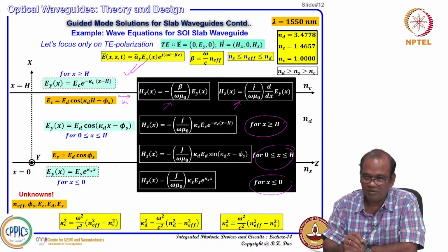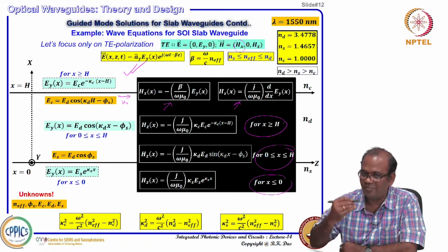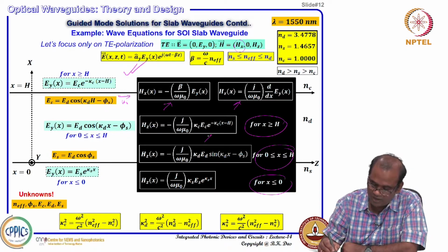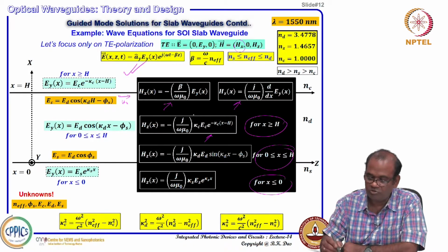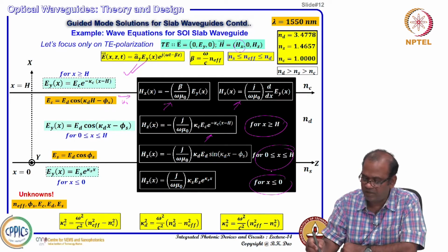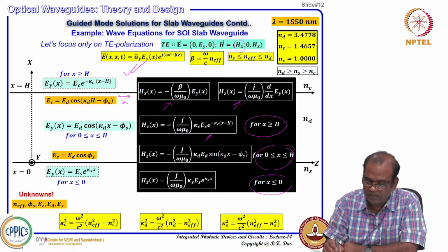You know tangential components are continuous at the interface. So, instead of considering the x component, I focus on the z component of the magnetic field, so that at the boundary I can apply continuity. That is why I directly found the tangential, or longitudinal, component of the magnetic field. Obviously, the x component is just proportional, you do not need to make any derivative, but for the longitudinal component you need to make some derivative. If you make a derivative here, minus kappa c will be there, j omega mu naught is there, along with that minus kappa c will be there, that is written.